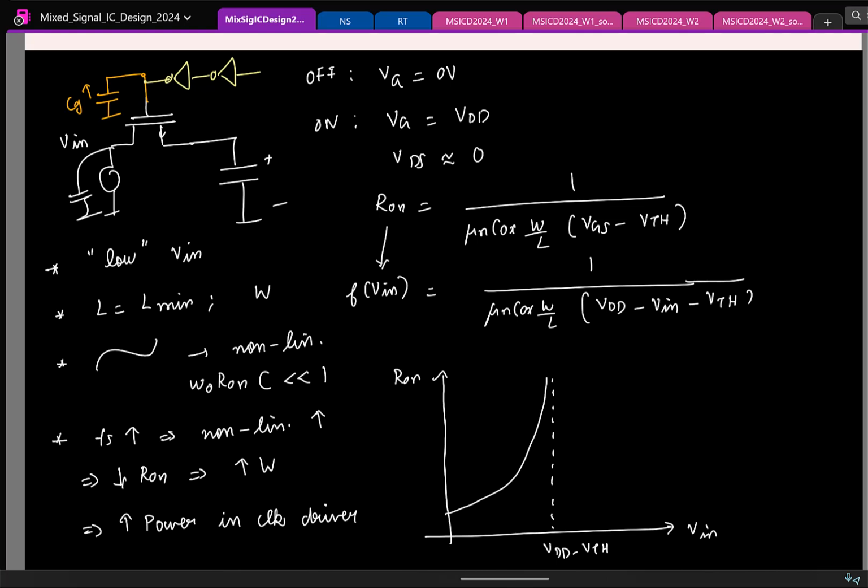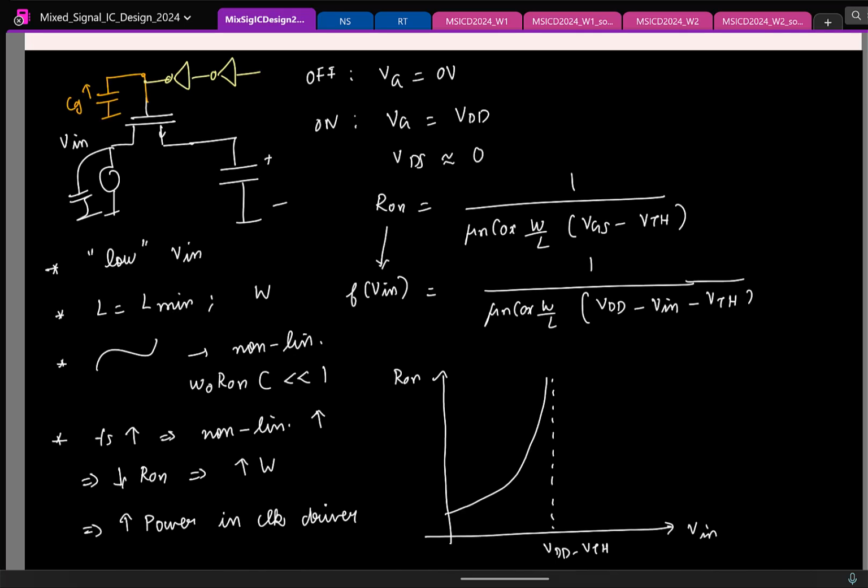So similarly, by duality, you should have something else that works for high inputs. Can we make a statement like capacitance increases, but majorly the gate capacitance? Correct. Yeah, that's true. I mean, we should be slightly careful. All capacitance will increase by the same amount, but typically the gate capacitance will be much larger than other capacitance. So delta C will be higher with respect to gate, but if you just see delta C by C, it might be similar.